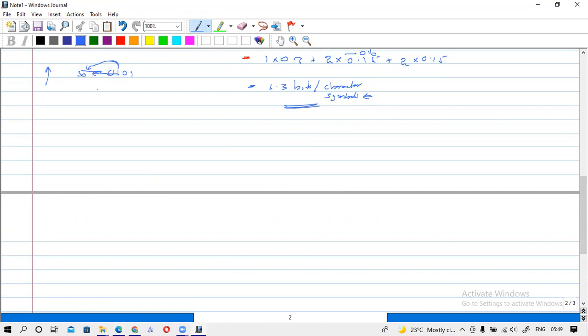For example, if you use a binary modulation scheme, that means binary phase shift keying or binary FSK, you assign 0 and 1 for a symbol. If you go to 4 PSK or QPSK, the order of the modulation is 4, so you assign 2 bits per symbol.